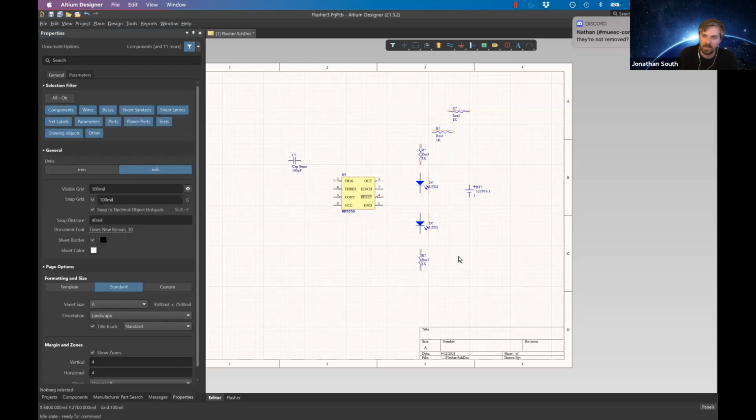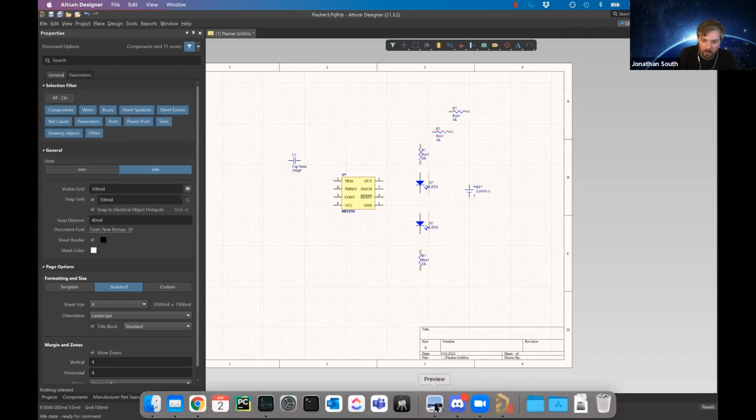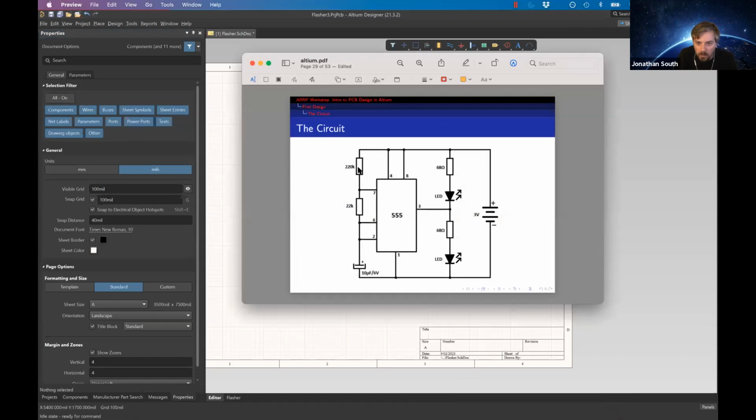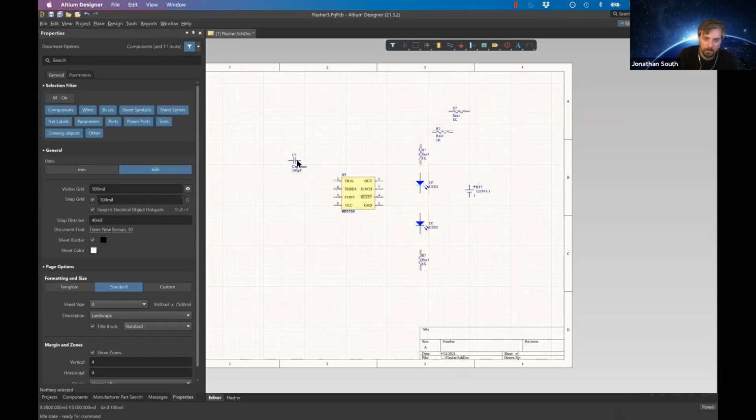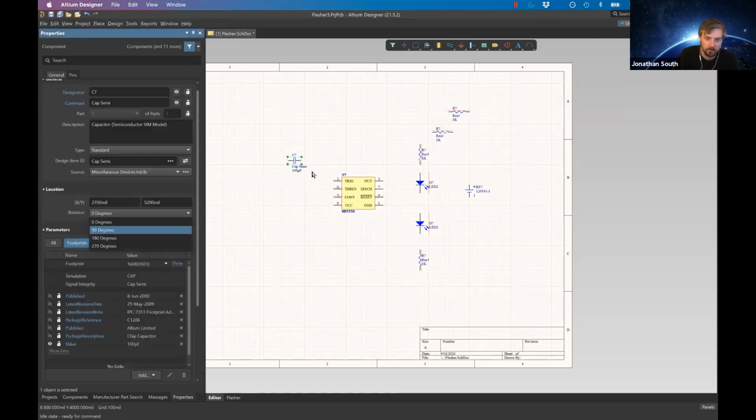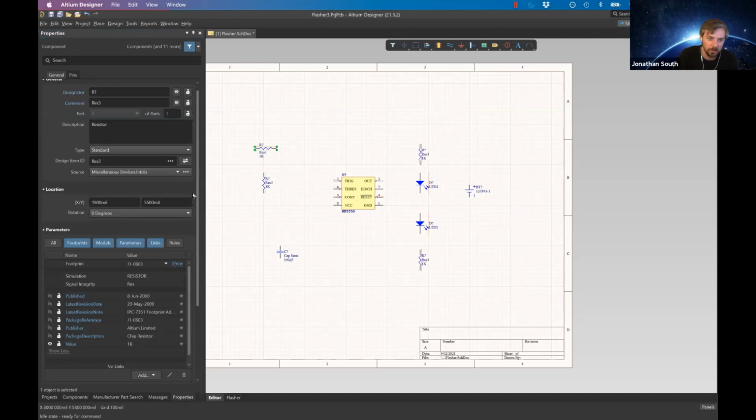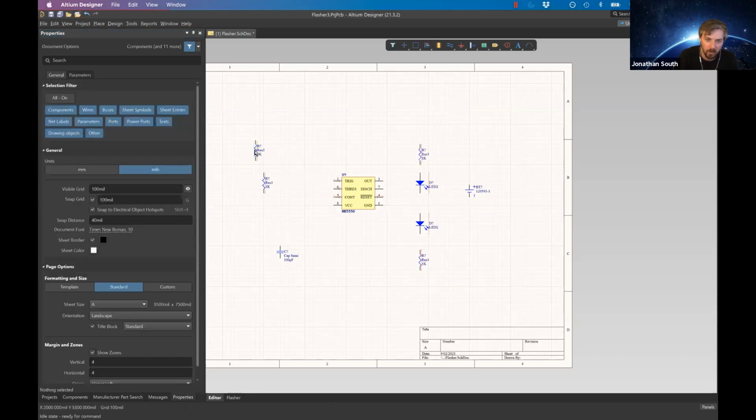So place your components first, and then we'll join them with wires, and I'll show you how to do that. So you've got to make sure your nodes are all connected. So that was there. We had 2 over there and a cap down there. There's probably a shortcut for rotate somewhere, but I can't be bothered finding it. Let me know if you do. I should probably try Control R or something.